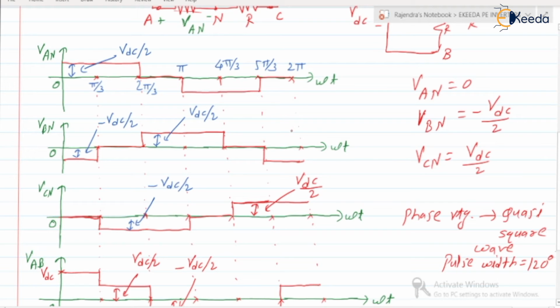Okay, so here apart from the sinusoidal, all the requirements of the balanced three phase voltages we are getting and it is fulfilled, it is matched. Are you getting the point? There exists a phase displacement of 120 degree. Peak value of all the three phase voltages is same and they are having the same frequency as well.